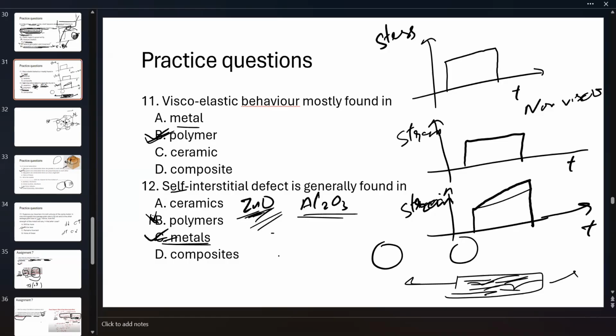Whatever the positions are in the lattice structures, for example FCC, there are atoms sitting on the corners and an atom sitting on the face. Since all of them have the same size, you get an interstitial void of some size, where an impurity can sit.